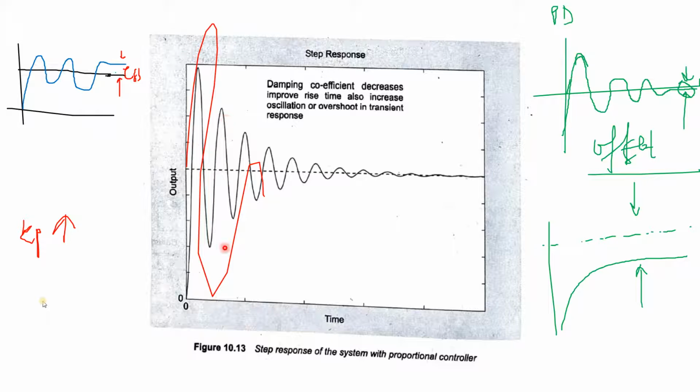So what is the advantage then? In the P controller, the overshoot was very high. Without any controller, the error is always very high. With the controller, the error can be reduced, but it cannot be reduced totally with the help of the proportional controller. In the action of minimizing the error, the controller increases the oscillation and the overshoot of the system.